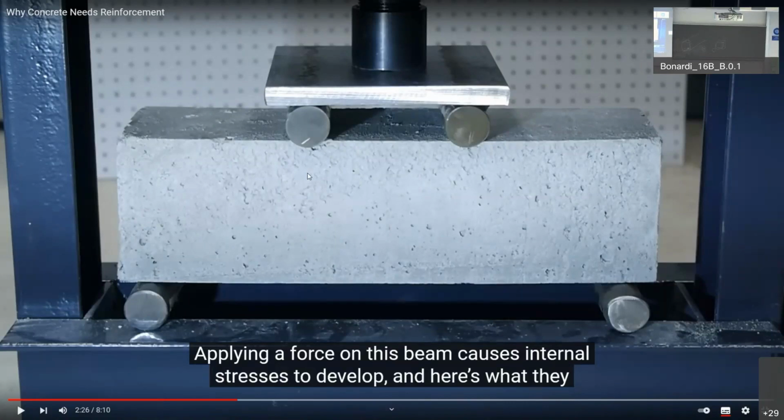And we have a vertical transversal load applied on 2 points. We can imagine that this load is half applied here and half applied here. So it is as if we have a horizontal beam on rollers, half of the load applied here, half of the load applied here. And we know, if we compute the diagram of the internal forces, that in the middle there is a constant bending moment.